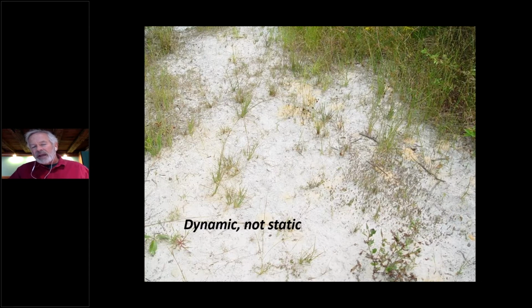So that's evidence of the bioturbation from soil invertebrates, where they're burrowing through this material, grazing on the roots, grazing on the microbial biomass, and keeping that system porous. So we haven't really had to do any kind of maintenance, which would definitely be required if this was just an inert sand cake, a filter bed. This is a living system.